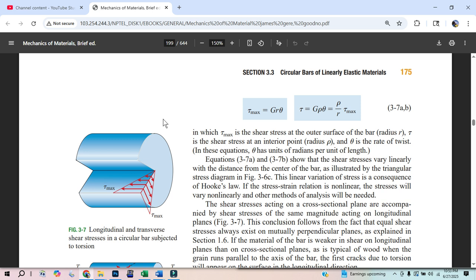There are some nuances with the vocabulary. But anyway, the face that you're actually putting the force on is the face that is facing the direction of pull. If I'm pulling this way on this cylinder, the direction this area is facing is perpendicular to the area. So that force is parallel to this face's normal. Where shear is the opposite.